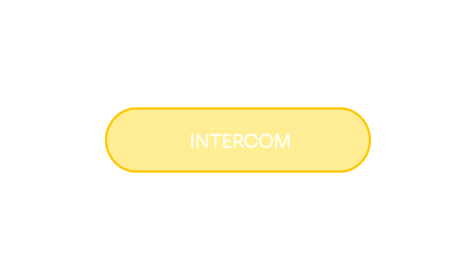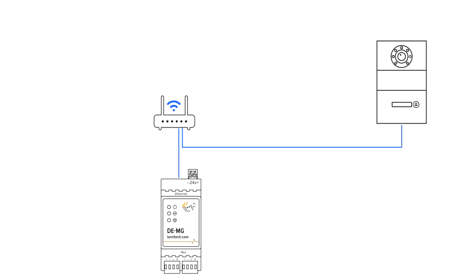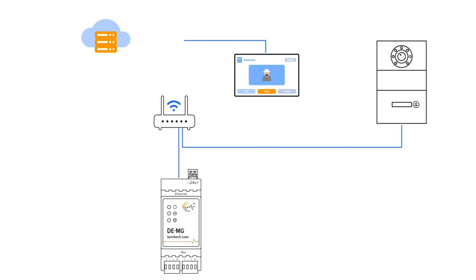Intercom. The Intercom FEIC enables both local and remote communication with visitors and features a built-in RFID and NFC card reader. The Intercom connects to the local network and supports both passive PoE and active PoE 802.3AF. Third-party intercoms supporting the SIP protocol can also be integrated into the system. For their integration, a SIP account provided by our company should be used. Internet connectivity is required for the operation of third-party intercoms.